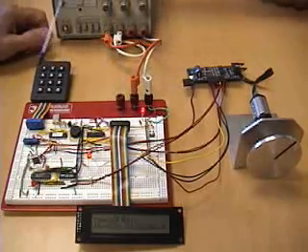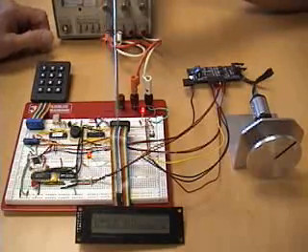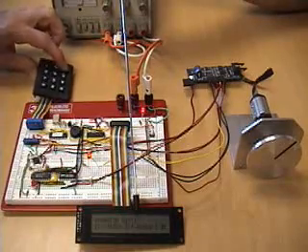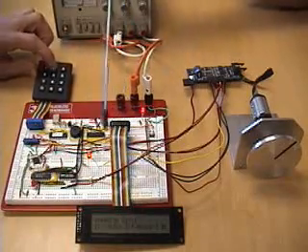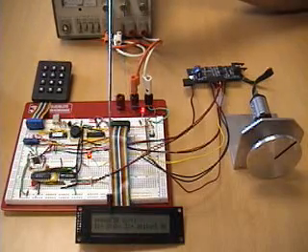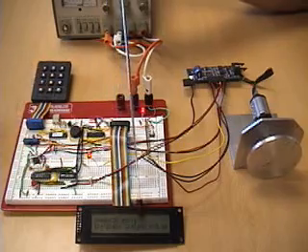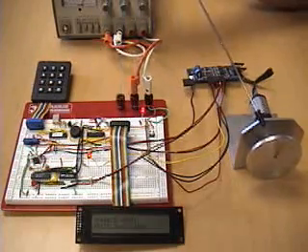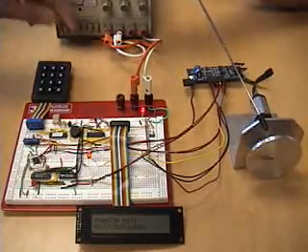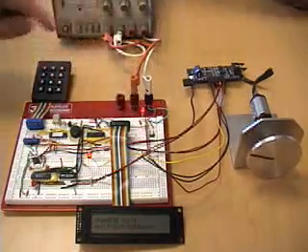By depressing the second key, we have the option of changing the speed, that's the rate at which pulses are applied to the motor, and whether the motor rotates in a clockwise or counterclockwise direction. By selecting 1, we will rotate clockwise, and by selecting a speed of about 50, we'll get a nominal speed. We execute by pressing 0, and notice the motor then rotates at a constant velocity based upon our input values, and then we can terminate that rotation with the stop button.